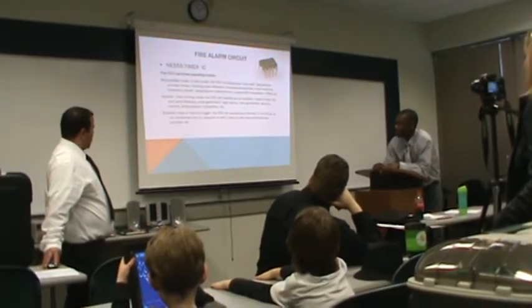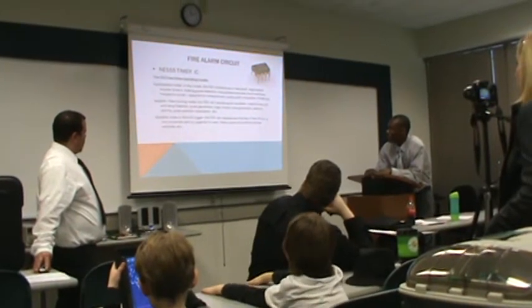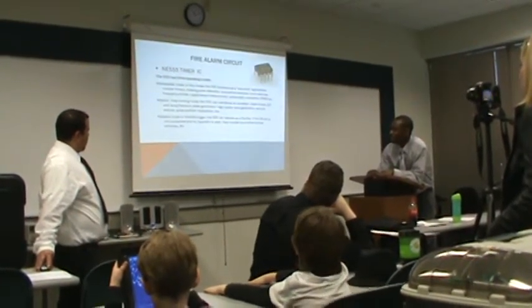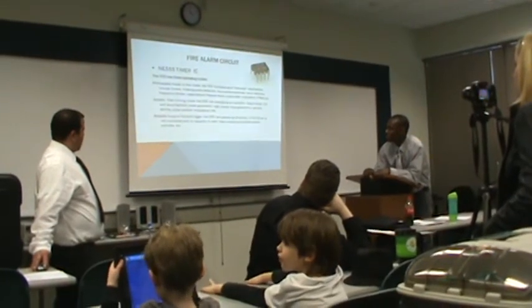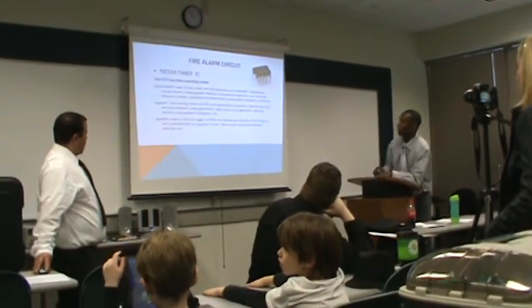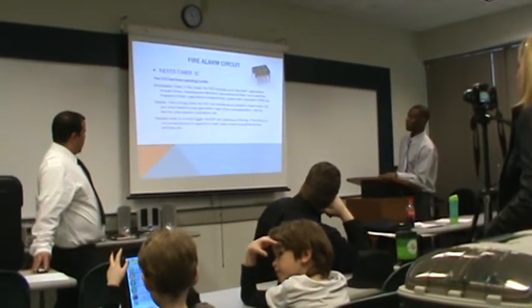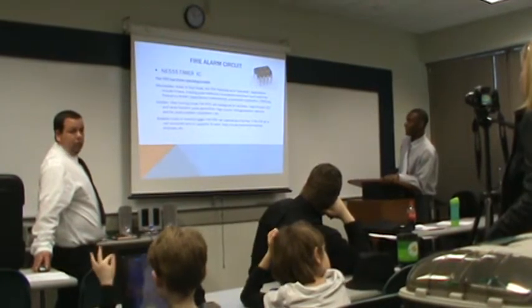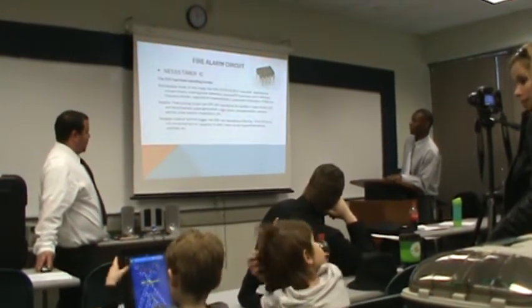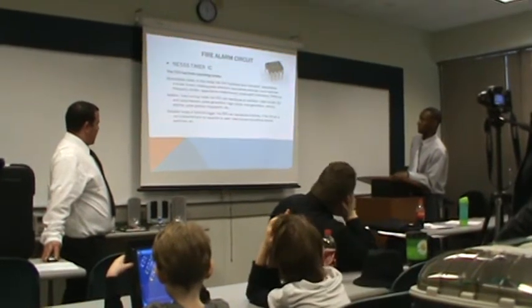Astable, or free running mode, uses include LED and lamp flashers, pulse generation, logic clocks, tone generation, security alarms, pulse position modulation, etc. In the bistable mode, the Schmitt trigger, if the DIS pin is not connected and no capacitor is used, uses usually include bounce-free latch switches.